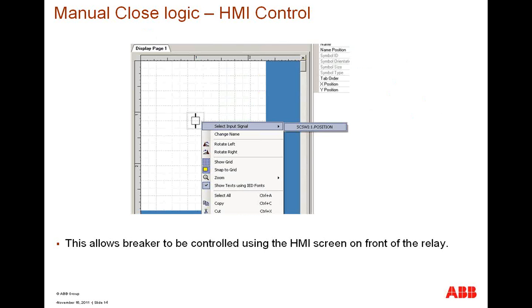For your manual close logic, to associate this to the HMI control, I'm depicting a circuit breaker on the HMI screen and associating it with the SESWI. This allows you to select open and select close the particular apparatus you want to control.